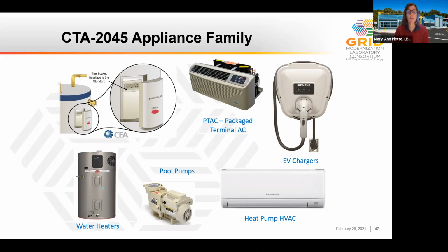So the CTA 2045 can actually read a Wi-Fi signal, it can get an OpenADR signal, it can get an SEP signal. So it's multi-protocol on the software side, and it's got a physical port. So you can retrofit a device, or you can get an EV charger or a water heater or a pool pump that has CTA 2045 available on it. It tends to be for individual devices.